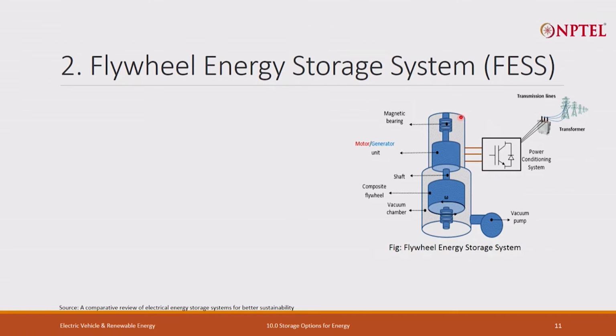A lot of technologies have been embedded to reduce the losses, very low friction, because generally the friction would be very high. So what do you require? Bearings, very low friction bearings. And when I say bearing, it's not only mechanical bearing, sometimes it would be magnetic bearing, sometimes air suspension bearing.